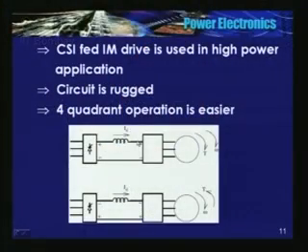See here, a large inductor, AC to DC conversion. I said we need to have a variable voltage here, regulated variable voltage here, which you can realize using controlled rectification, and a 3-legged inverter feeding a machine. So at any given time, operation is in the first quadrant. T is also in this direction, omega with plus minus plus minus.